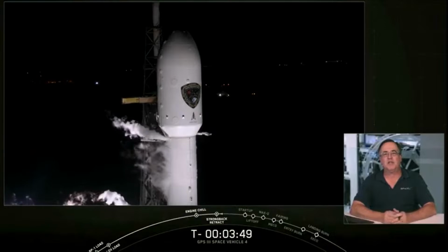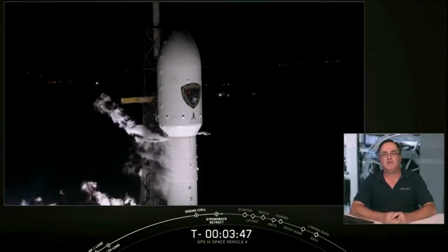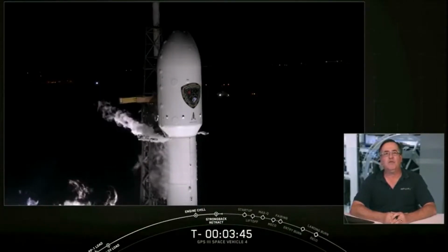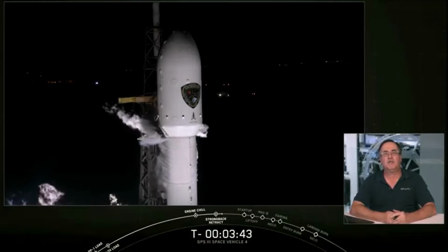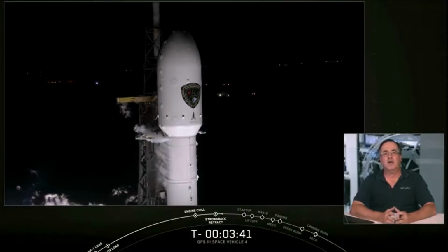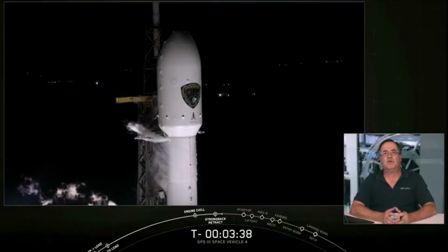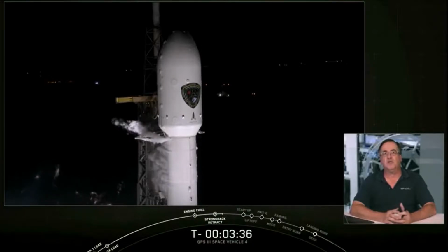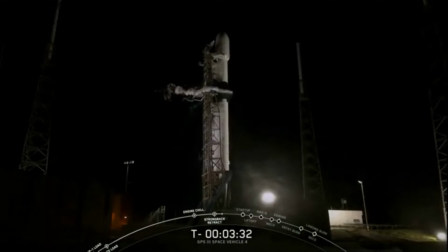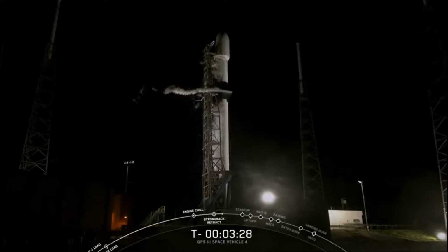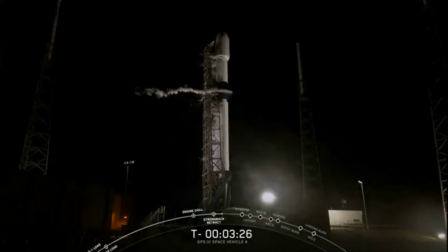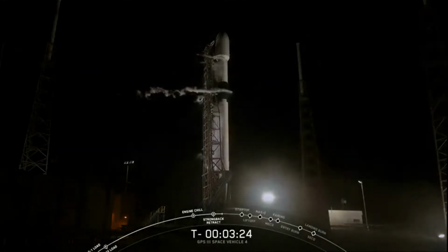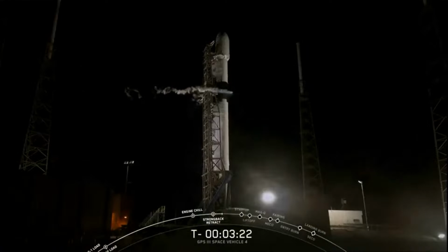We've pressurized the stages as part of that. And right now we are moving away, like I said, about 2 degrees away. At liftoff, hydraulics will then pull the strongback to a position that's 45 degrees away from the rocket to make sure we're clear for liftoff. Now, first stage fuel loading did complete on time at T-minus 6 minutes. We're waiting to hear first stage LOX load complete at T-minus 3, and then a minute later, LOX loading on second stage.